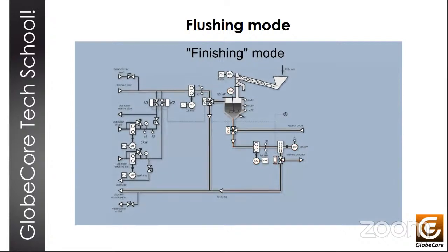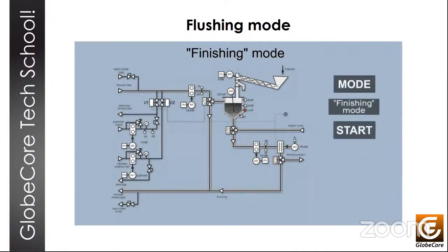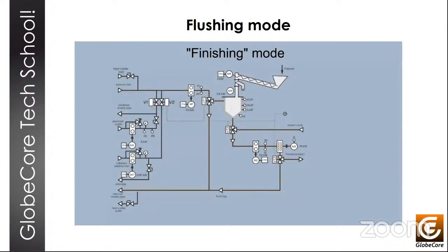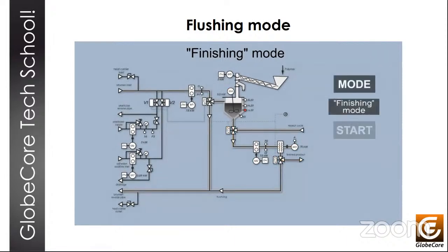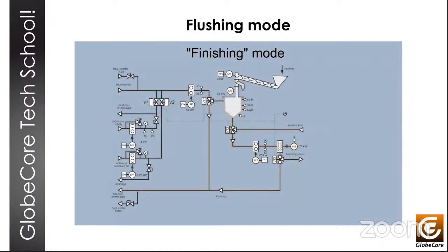And when the low-level sensor, the LLS1, is off, the VT3 pneumatic valve switches to supply bitumen to the outlet. The M4 mixer stops, and the bitumen from the mixer starts flushing that pipe to the finished product storage container. And after a certain time, when the mill current falls below that set point, the M2 pump and the M3 mill are also disengaged.